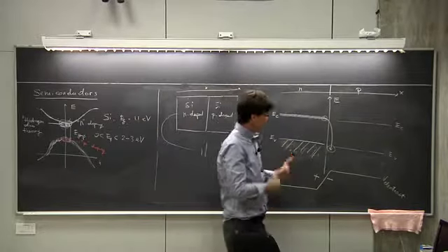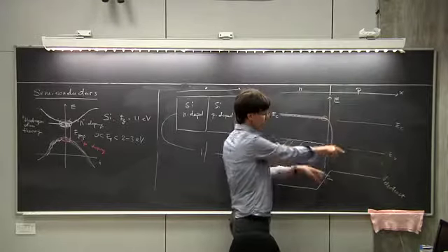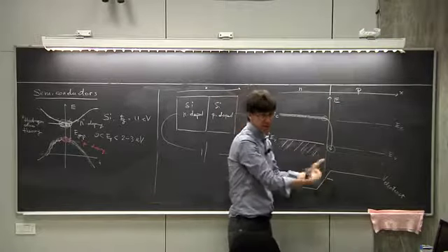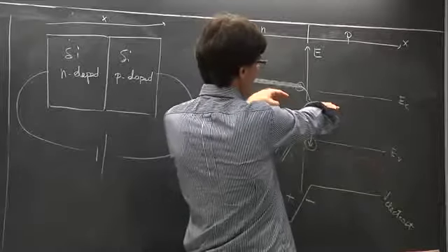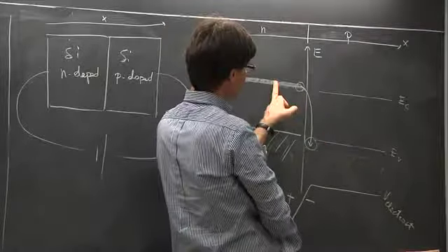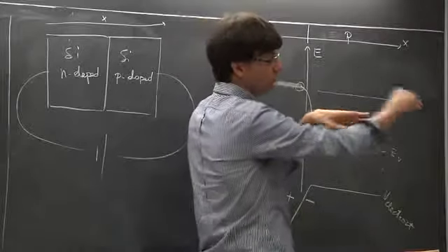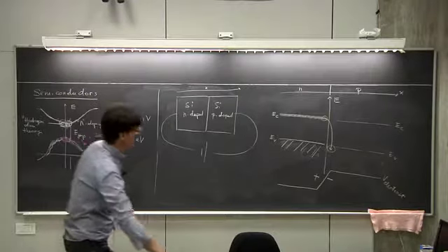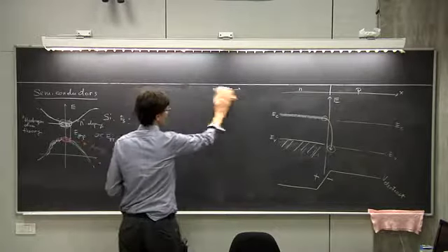The more I move charge to the other side, the more I gain energy, but at the same time, for electrostatic reasons, this level will move up with respect to this one. So I'm creating a barrier for myself, and the whole process will stop when this level is aligned with the conduction band. The conduction band on the left side will be aligned with the valence band on the other side, because this is the position in which there is no more gain of energy in transferring electrons from one side to the other. Okay, so the resulting final structure that I will have is the following.